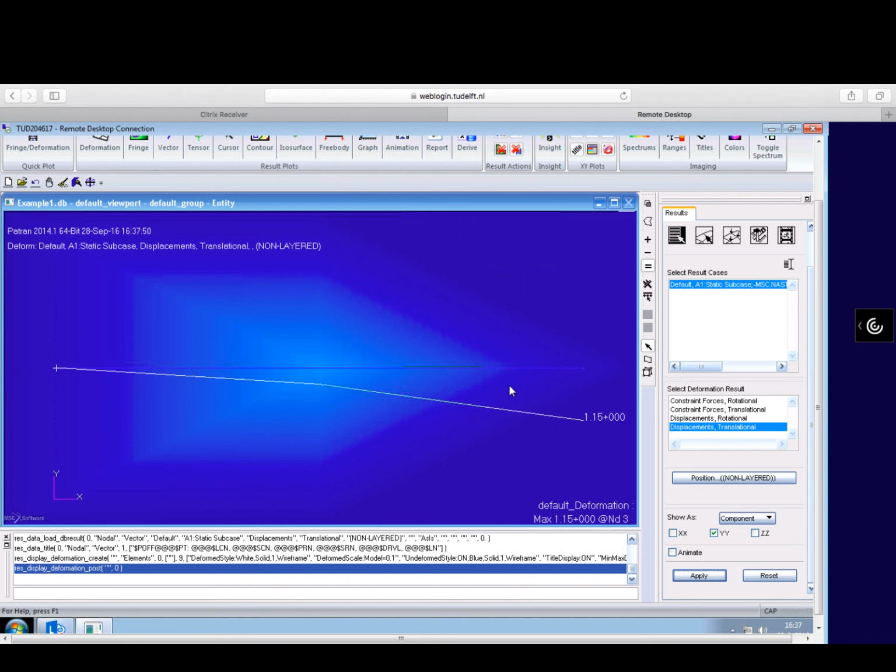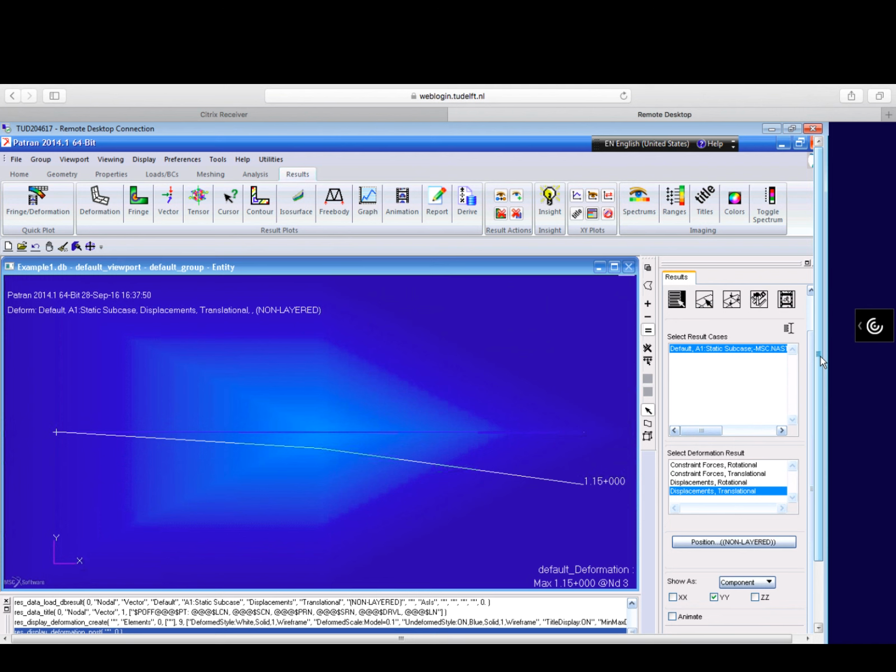So you see that if I keep increasing the number of elements, I will see a much smoother transition, but it's not going to change anything in terms of the result. That means I can use a certain number of elements already for a convergence study that is getting close to the result that I need. Well, I finished the complete analysis with ABAQUS by using 4 elements, 8 elements, 16, 32. In ABAQUS, the element description is slightly different than PATRAN, and it took some number of elements to get to 1.15, whereas for PATRAN, it automatically got to 1.15 with the way it has been described.